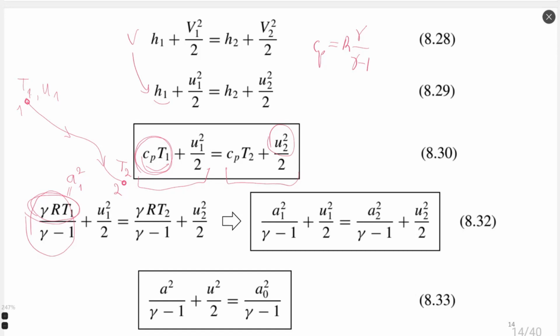So you can say what will be speed of sound directly from this equation if you know the left side, for example, of this equation from initial condition or inlet condition, or you measure it already, you can find relation on velocity and speed of sound at any other arbitrary points, a point in this system, or several points, because we can write just not for 1 or 2 points, we can write for 3, 4, 5 points, as many as we would like.